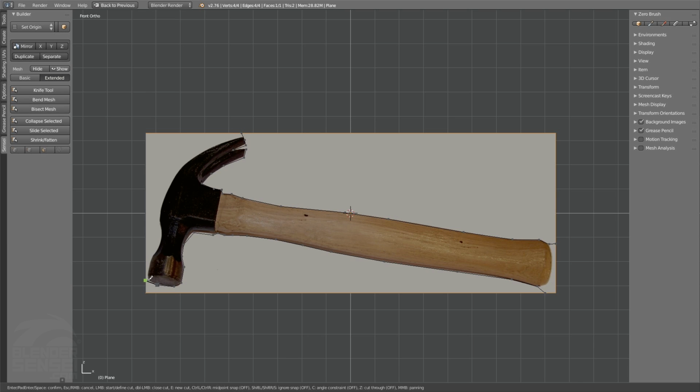And notice here that my cursor is wanting to stick to the side of this edge because auto snapping is always on. So we can temporarily disable that just by holding S. Notice now that it won't automatically snap to it, so we can get right around this edge how we want to. Then we can pull this up here, do something like that. And so we've got these two cuts here. I could tap space to go ahead and apply those.